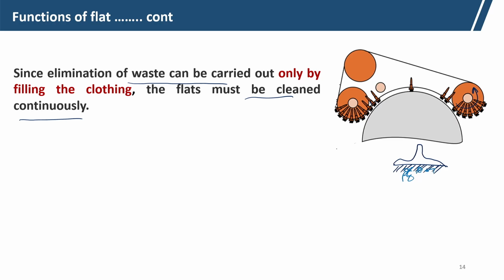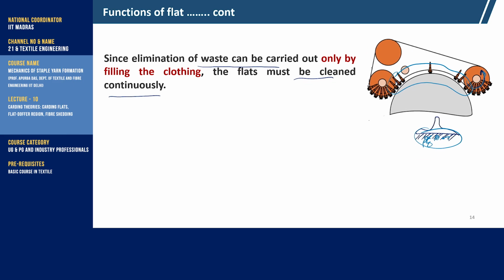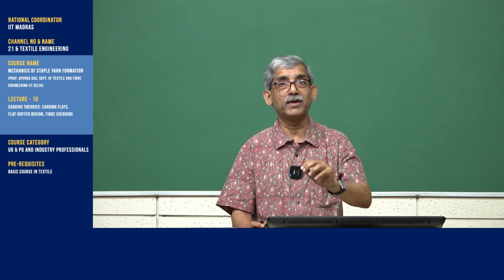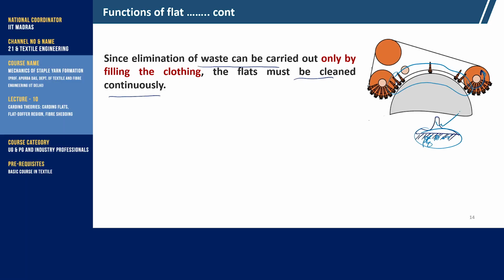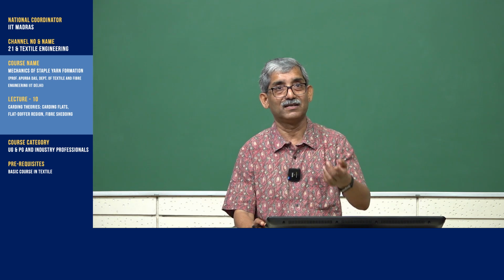Otherwise, if it is stationary in the carding zone, it will be blocked. After a certain time the flat wire points will be loaded with the short fibers, naps and all this waste material, and then the carding performance will deteriorate. So, we need to clean it continuously.